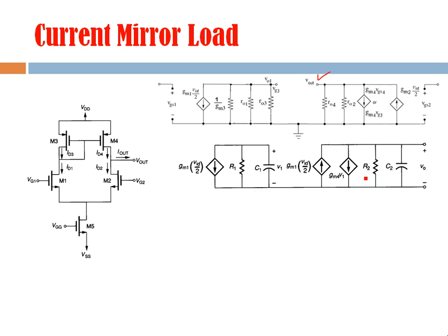together represented by this R2, and we have assumed one capacitive component which is between the output terminal and ground. So that is indicated here towards this side, and our final output is here, V0. Now, this R1 is the parallel combination of these three resistive components. It is shown here, and it is approximately equal to 1 by gm3, because this gm3 is very large.